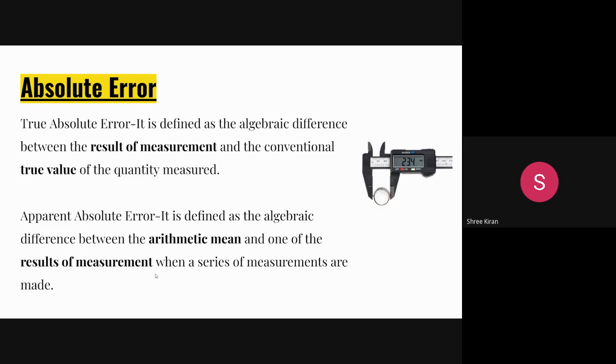So apparent absolute error may be due to some scaling operation or metal removing operation or some manufacturing operation or some shaping operation or some design constraint or design aspect. All this comes into account by the time of manufacturing, and there will be changes in some values. In all the cases there will be tolerance, like we can have an excess or minimum value of 0.02, 0.01 or 0, or in some cases maximum 0.05 also. This is what happens.